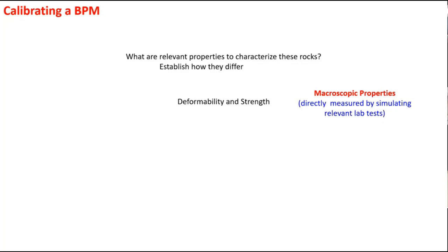We could take the rock and machine in a crack, and now we could pull it. And at some point, boom, it would rupture and the crack would shoot across both surfaces. We could call that the strength. Notice that that thing is loaded in tension. It's a different kind of strength. If it's loaded in compression, maybe we use UCS. I could go on. I haven't elucidated all the different rock mechanics tests.